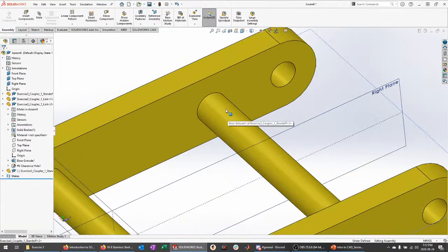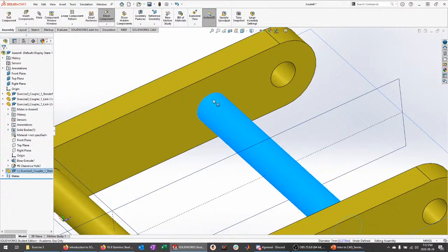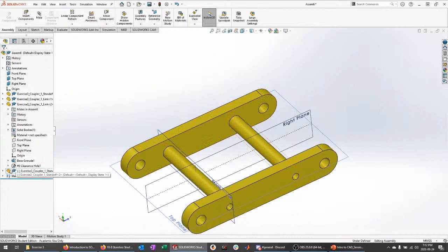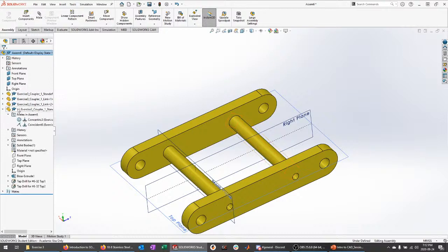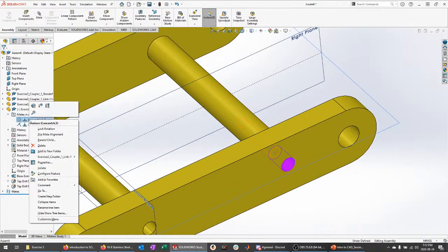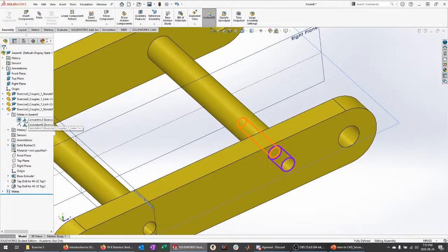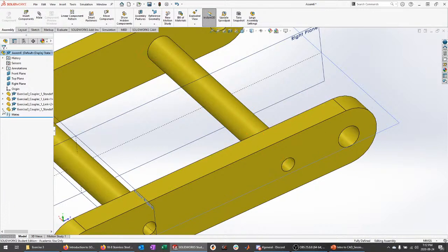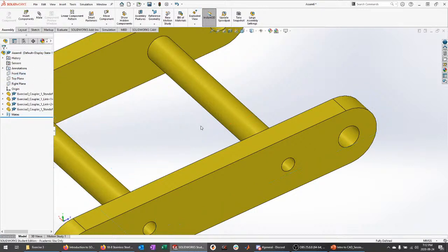And now, it's very difficult to see because there's no frame of reference, but this part can still rotate. It doesn't really matter what orientation it's in, since it's an axisymmetric part, so I'm just going to navigate through the drop-down menus to that concentric constraint. I'm going to right-click and lock that rotation. Just make sure everything's fully constrained. That doesn't matter too much.